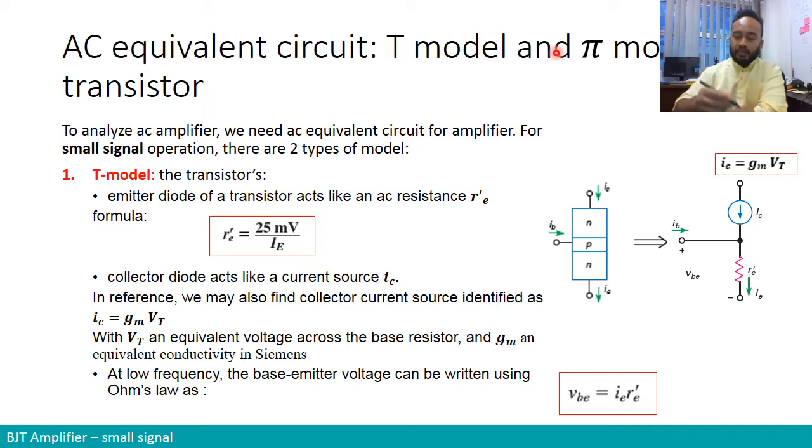Okay, so having understood all the potential problems of using the amplifier and the condition that we have set, which is what we call a small signal, we can now try to analyze our amplifier. But to analyze our AC amplifier, of course, analyzing a circuit means you have to analyze all the characteristics like voltages and currents in the circuit. So instead of just drawing a BJT in the circuit, we may want to model the transistor as a simpler component that reflects its behavior electrically.